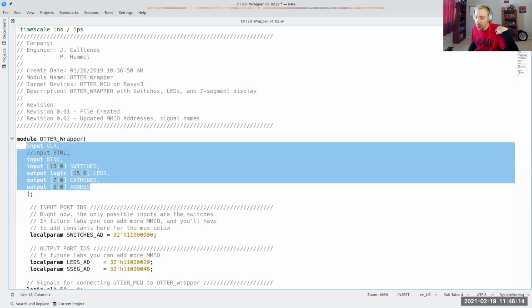These will be all the things that you will add constraints for. So this file you should be able to just add to your hardware 7, and it should then become the top module. We now have a wrapper with the CPU inside it, with all of the other stuff inside of it. So modules inside of modules inside of modules.